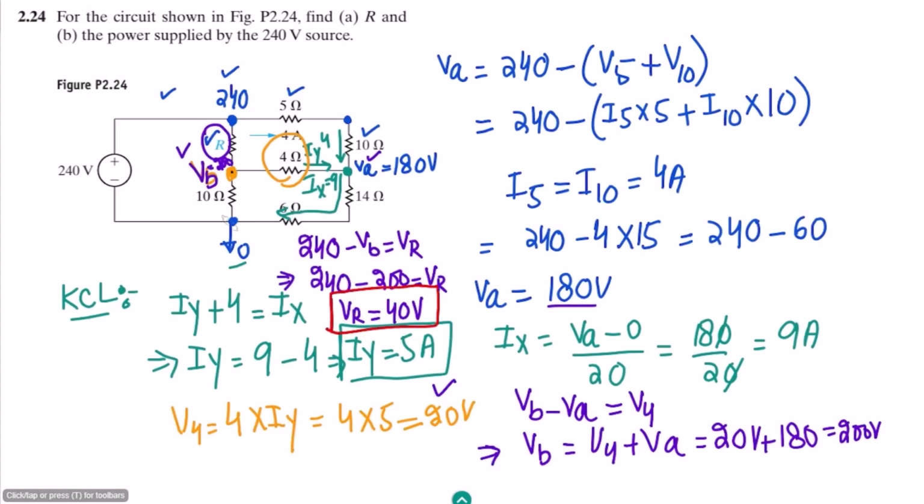The other thing which we have to find here is this IR. Because once VR and IR are found out, we will easily find the value of R, that is VR divided by IR. We will be using this formula. These two are known, but the IR is still unknown. If this is the current which is the applied one, going through here, we can see that this is the 4 amps and the remaining one would be here. We can find it out as well.